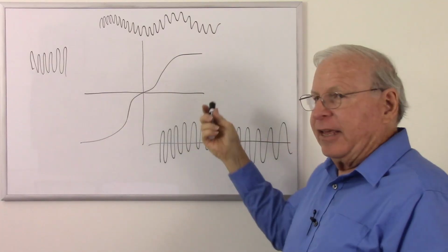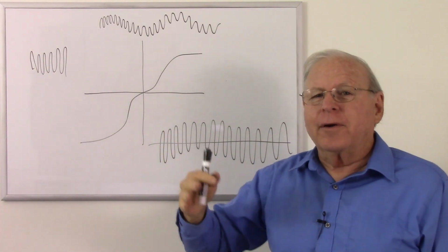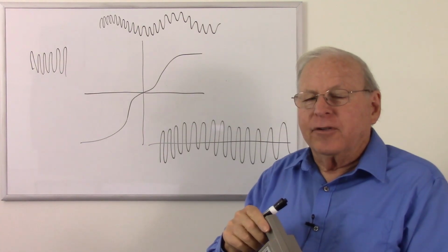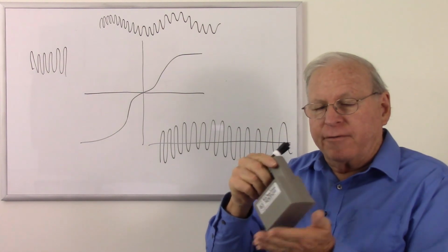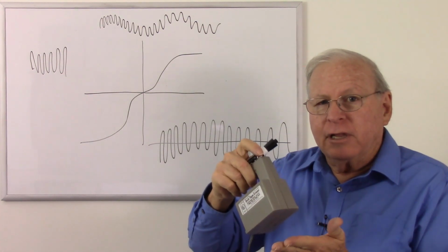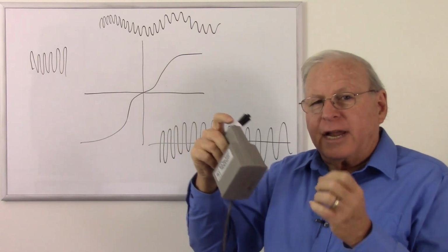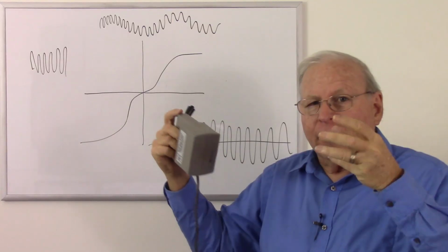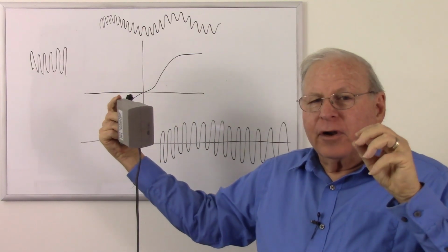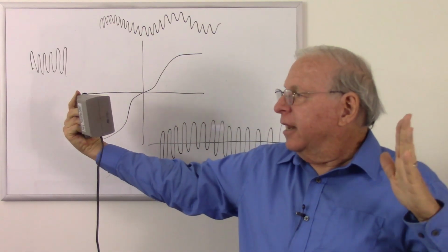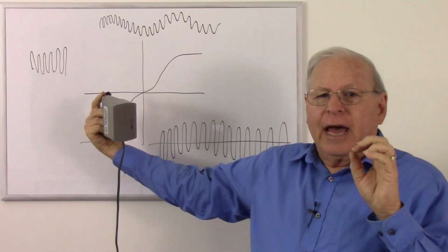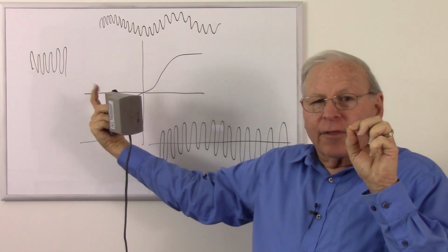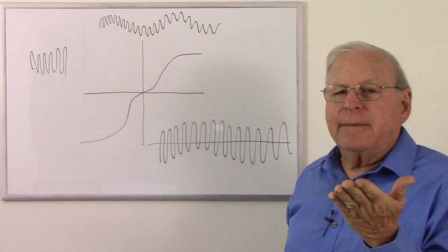So that's going to add a DC bias to my tapes. What did that do before? It caused noise to have those magnetized domains on the tape. So to make sure that they weren't there, after I'm really through, I slowly move them apart. So now the magnetized domains are switching back and forth, smaller and smaller and smaller, until I get it as far away as I reasonably can, like about 3 or 4 feet. Now those domains are just flipping very small, almost no magnetism at all. Then I release the button, and now it's completely demagnetized.